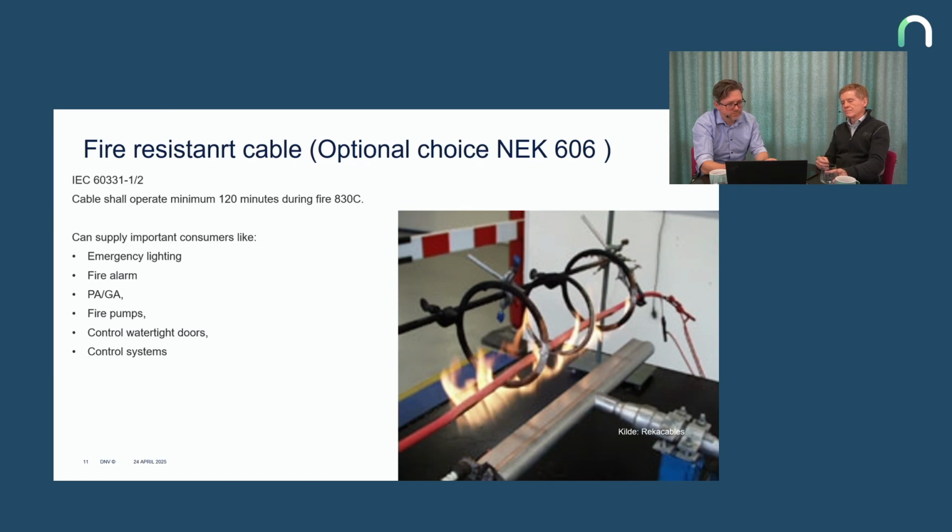Yes, and this is just another test, a fire test. That is for important cables where we have to ensure that this cable will maybe not survive a fire for a long time, but at least work for, let's say, 1 hour, 2 hours. Normally it will not break down immediately.